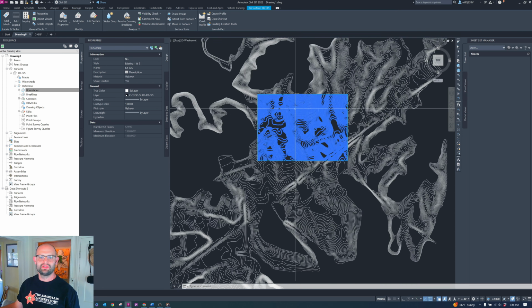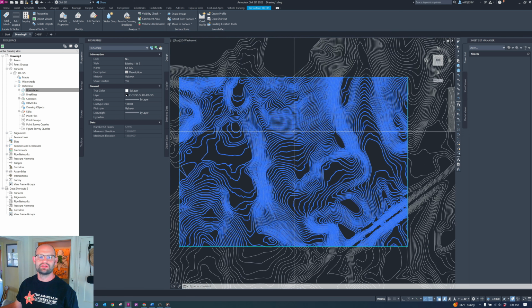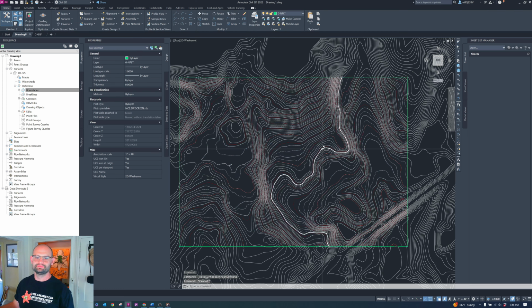I have the surface selected, and I want to get these polylines in my base file over there on their correct layers. And now that I have this style set up for the surface, I can go up to the top ribbon over here. Click Extract from Surface, scroll down to Extract Objects, click that, and I don't need the border to repeat, so I'm grabbing the major and the minor contour, hit OK.